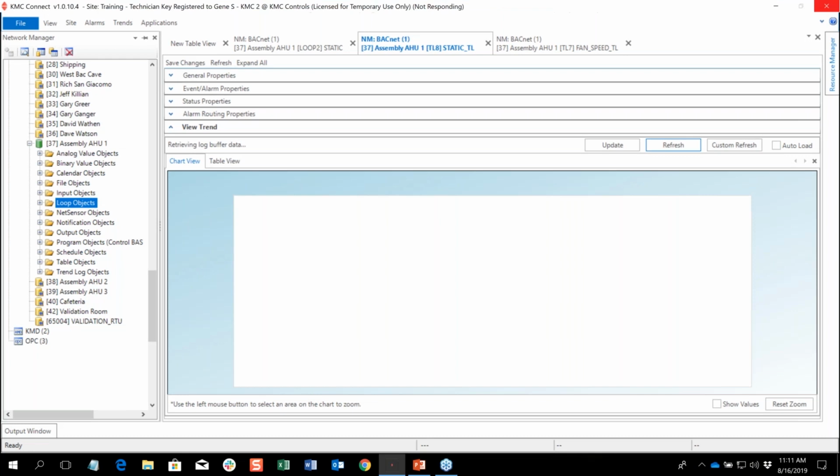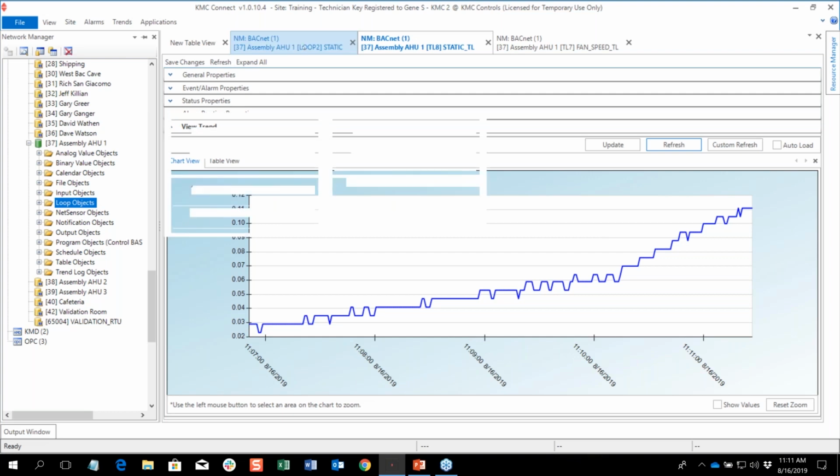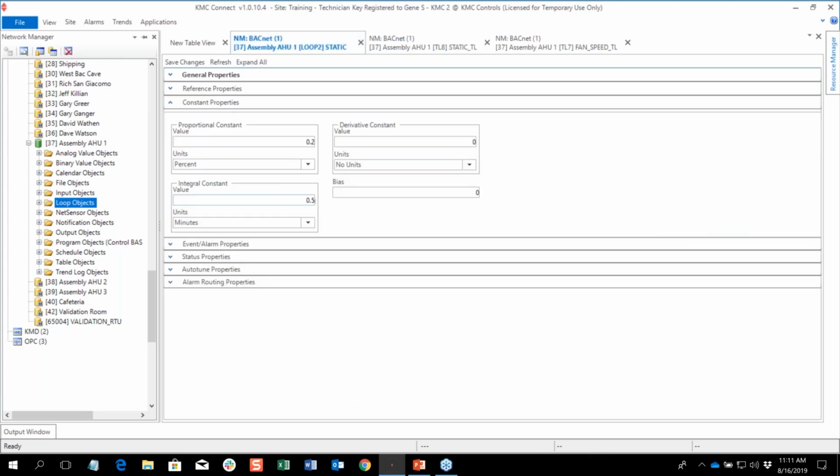Okay. As you can see, we're being pushed up towards the set point without introducing oscillation. So we can add, let's do another step one more time. Maybe I'm being just a little bit impatient, but we're going to go ahead and add some more integral again.